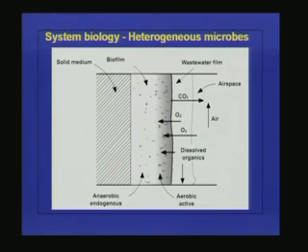wastewater. The factors that affect the oxygen transfer are: one, the overall oxygen transfer coefficient. Second, the concentration of oxygen at the solid liquid interface. If the oxygen concentration at the solid liquid interface is very high, naturally a high concentration gradient will be available between the liquid film and the biofilm, so naturally more oxygen transfer will take place. And the next one is how much dissolved oxygen is present in the liquid film. That is also important, which decides the amount of oxygen transferred to the system.